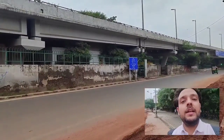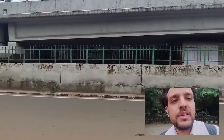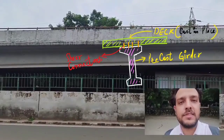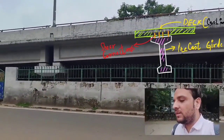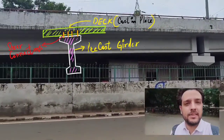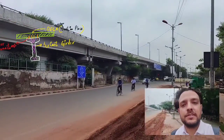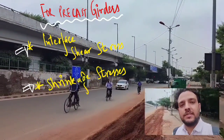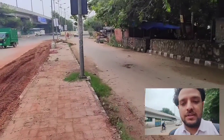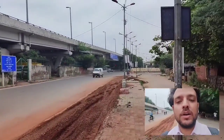In precast beams, one major difference is that to ensure composite action of the deck slab with the beam, you have to provide shear interface studs, or what we call shear interface reinforcement, so that the composite action between the slab and the girders can be ensured at all times. In that case, while designing such structures, you have to check for shrinkage stresses as well as interface stresses. Now we will discuss the variation of the cross-section of a T-beam along its length and how it is decided.